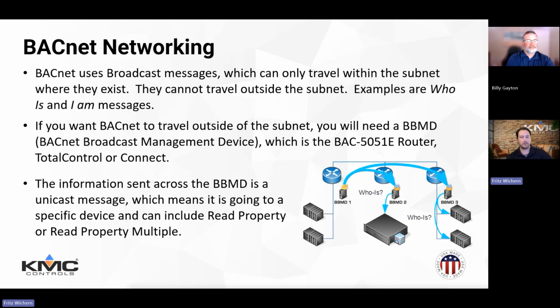It's a way to tunnel BACnet broadcast messages from one IP subnet to another in the form of directed unicast messages. BBMD is needed because IP routers block broadcast messages. And in BACnet, those messages are essential to discover and communicate between devices. That's how we get important information from building 1 to building 2. So those BBMDs are important, right?